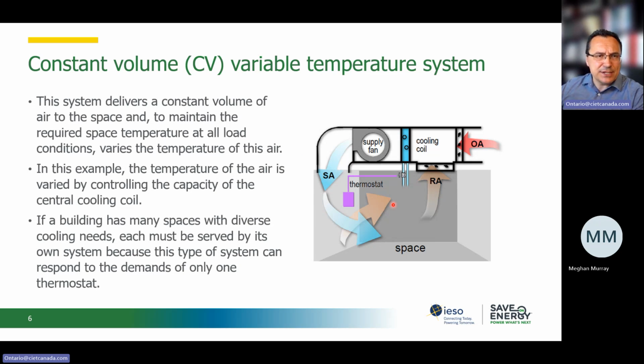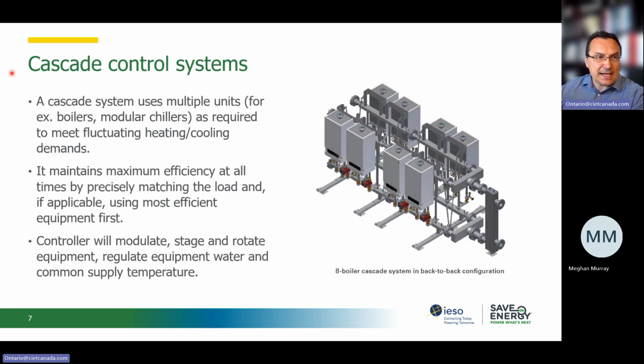And because we design our systems for the worst case scenario, that means that we operate the system at part load for most of the time. In order to increase the efficiency of the system, sometimes we are relying on a number of systems that combine, because systems designed by manufacturer for a specific maximized efficiency at a range of capacities will not work properly in some operating conditions, like for instance low load or different input parameters, like for example outdoor air temperature. So in those cases, we are using a concept called cascade control systems.